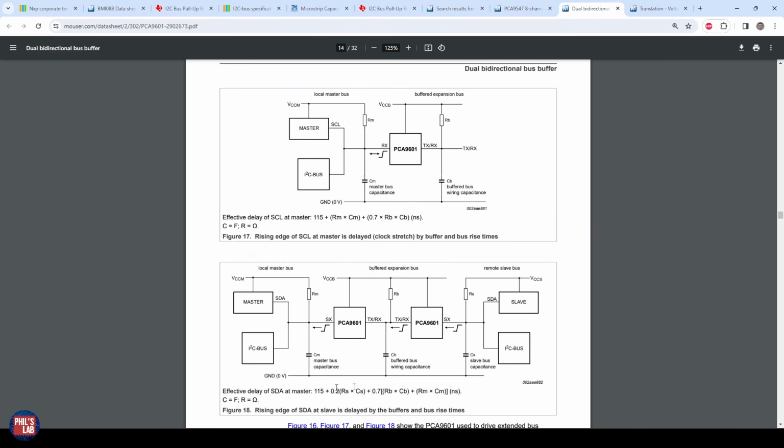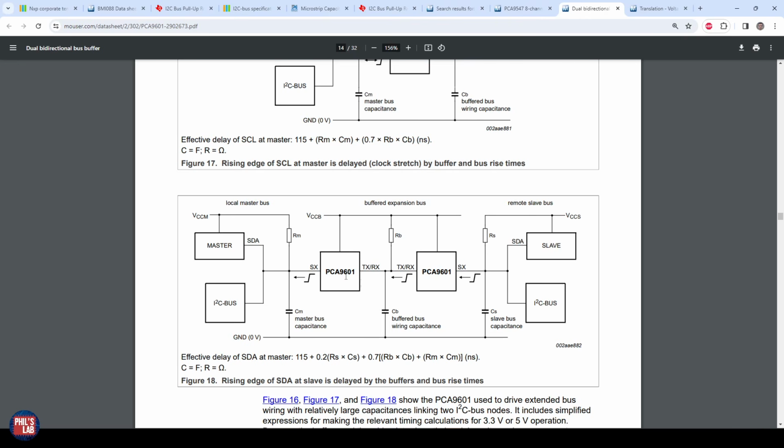And typically then a connection might be like so. We can use multiples of these buffers. We do need pull-up resistors in between every time we, so to speak, jump from one side to the other side of a buffer, as you see here, and this is always outlined in datasheets.